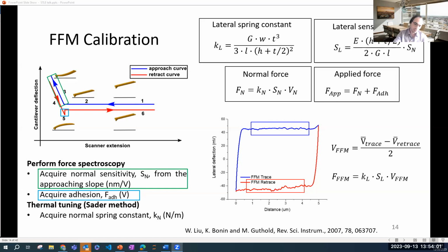Basically, you run the cantilever on top of that wedge, you get the forces there, and you calibrate it. While you can find commercially available wedges to calibrate sharp tips, it's not that easy to do with colloidal probes because they are much larger. There's another, more appropriate technique that I mostly use in my experiments, which uses beam mechanics.